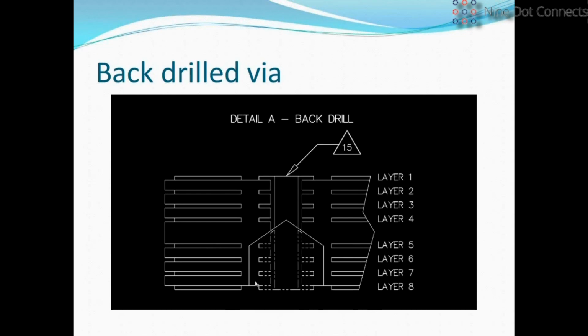So this is a good way of solving the fact that, hey, I'm going to have a solid piece of aluminum on the back of this board. I don't want any hot vias touching that board, and I don't want to worry about signals coming in contact with the enclosure. Just kind of throwing this out here to tease you guys, and hope you'll come back for more information.